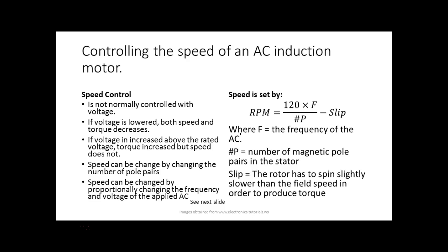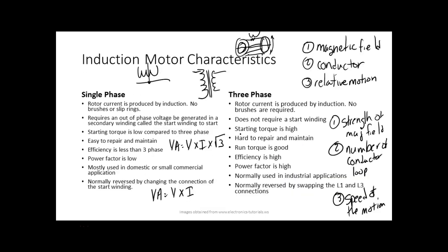Anybody know why? So we start off with a rotor sitting in there. We throw power on our stator, and it's doing 60 cycles per second, so we get a bunch of cutting. The rotor starts turning, and the rotor is catching up with the field. So if the rotor's running at 5 RPM less, it would only get 55 instead of 60, right? So what happens is the speed of the motor goes up. What changes?